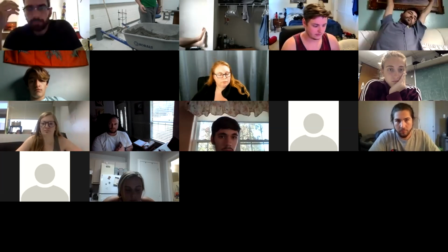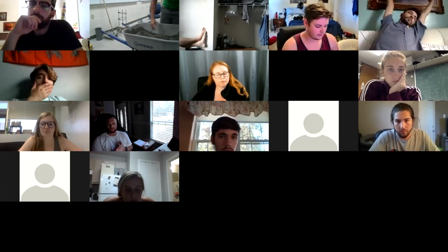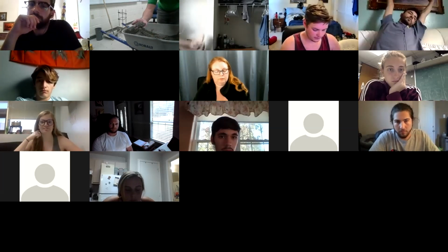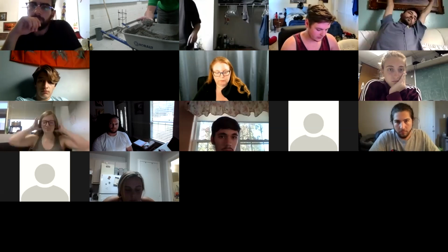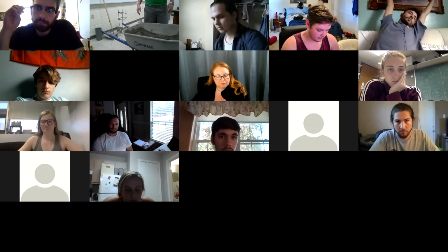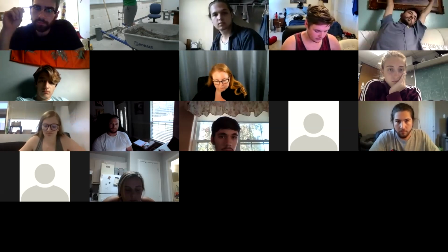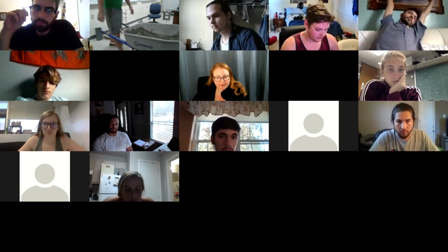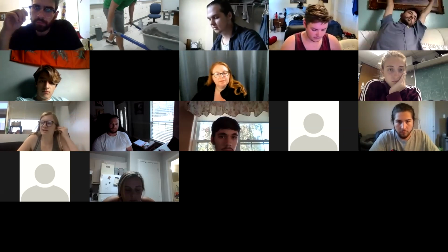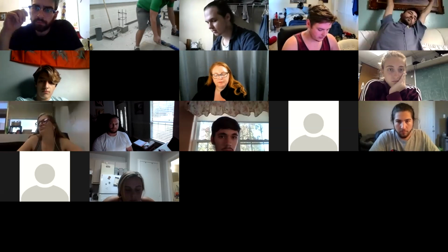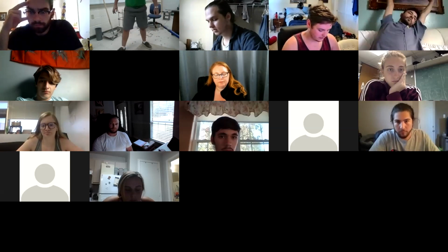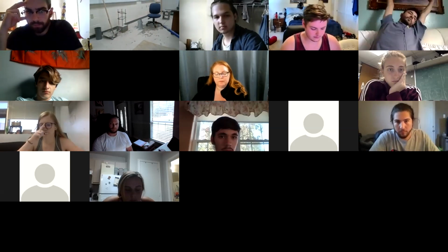Okay, now we're going to check the workability. Slump test. Looks like oatmeal to me. Does it look like oatmeal? I believe so. So now it is time to prepare for the slump test. I'm going to move it a little bit. So the slump test is going to be taking place right here. Let me see if you can see it.